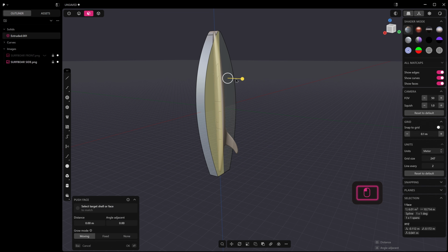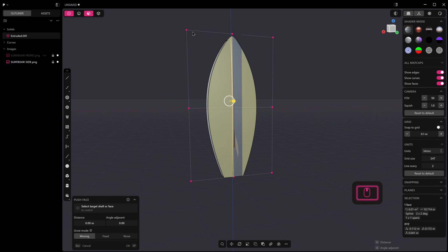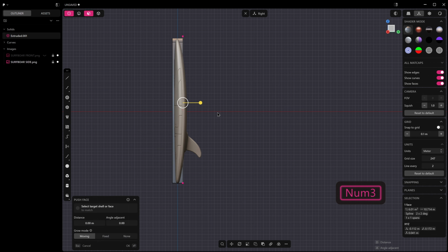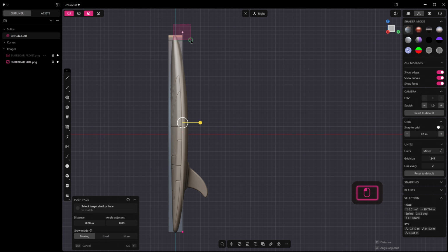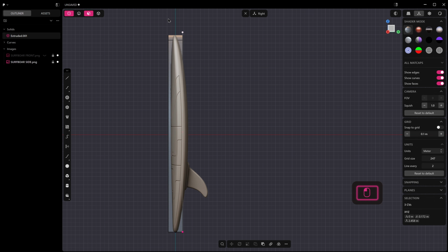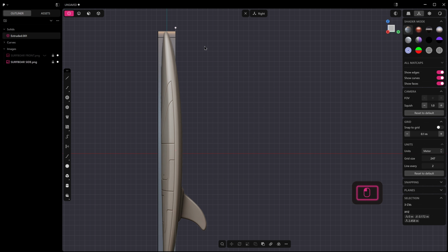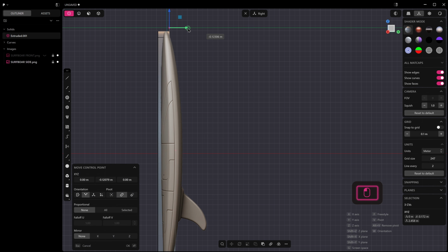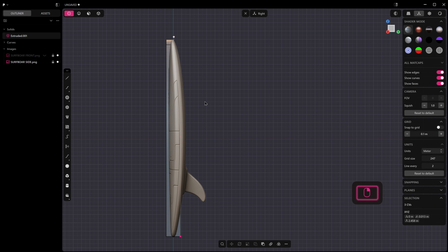So I'm going to select this face again and press subdivide again until we've got these 9 points, right? And then we can go into wireframe mode and use our pink marquee, going left to right, just to select the points only. And you see again, I've got the face selected there. That's because I selected the face. And then we can press G and drag this across here.